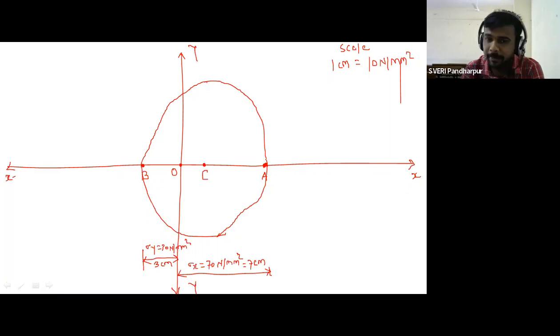By selecting the same center point, you have to represent the 2 theta angle by using the protractor. So you have to keep the protractor at point C. Why do we have to represent the 2 theta angle by selecting the reference point A? Taking point A as the reference point, we have represented 2 theta in the anti-clockwise direction. This is the standard procedure.